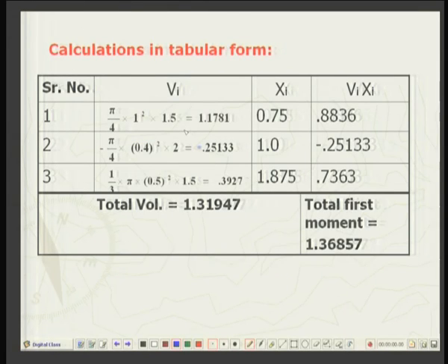So, you take the centroid of the cylinder, that of the cavity and that of the conical portion. So these are the values obtained from the handbook. Well, for cylinders you know very easily, half the axial length. So 1.5 divided by 2, and similarly 2 meter is the length of the cavity, so 1.0, and for the cone you can get it easily from the handbooks, and then you take the moments.